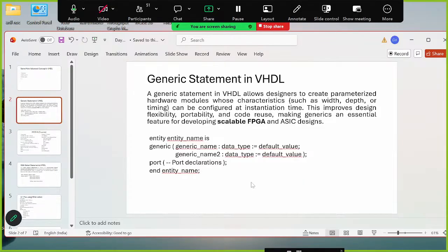If you remember, when we discussed standard IPs, I took the example of the adder-subtractor. That adder-subtractor is configurable in the sense that the range of inputs varies from 1 to 256. You can customize that particular IP as per your requirement for 4 bit, 5 bit, 6 bit, 8 bit, 10 bits.